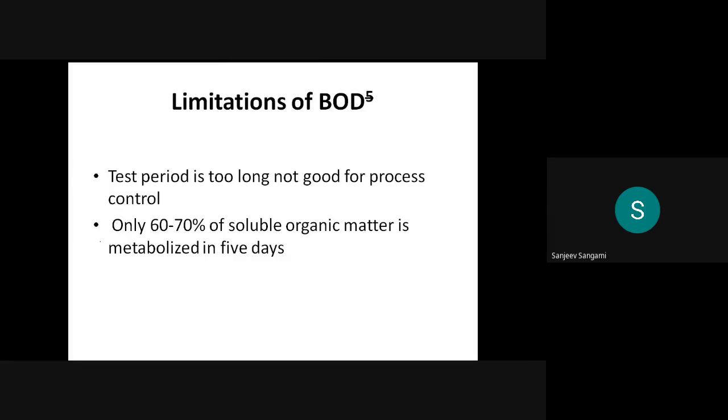Then, what are the limitations of this BOD5? I already said that the first one, it requires 3 days minimum, 5 days. If you want to find out how much BOD is present in the water, minimum 3 days is required. 7 days up to 20 days is required if you want to find out up to 90 to 95%. Still, it is not complete. That is one limitation which is there in the BOD test. And you have to maintain the constant temperature in the BOD incubator for 3 days. Even sometimes if the power has any problem in between, you won't get the exact BOD value.